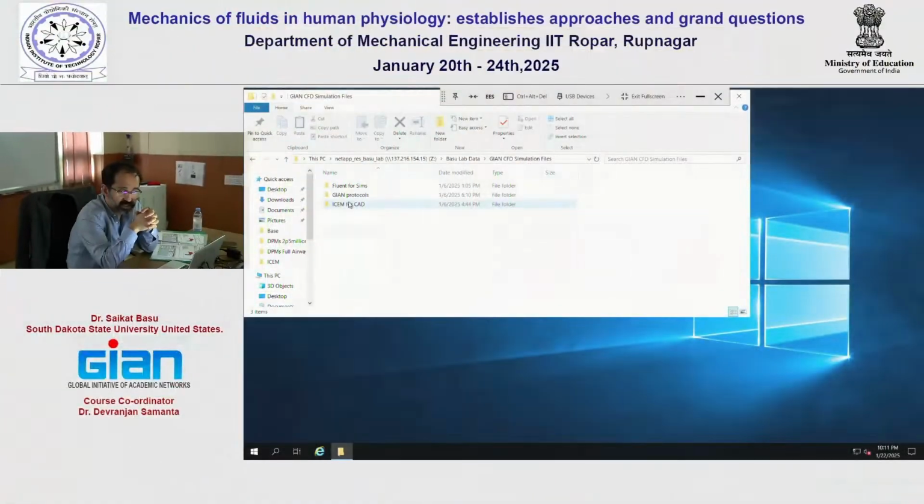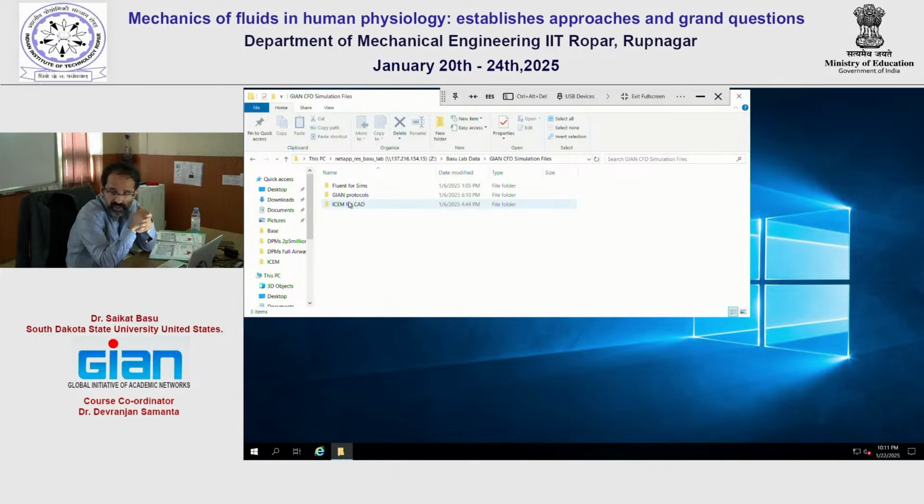But along with just meshing on the CAD software, we also do the region separation. So as you saw in the work that we have been doing, on the second day, I showed a geometry with all the sinus cavities marked out. You can do that on ICEM simply, or based on the question, you figure out what target sites you have to track in terms of particle deposition. So the geometry that I'm going to show today just has the nasopharynx marked out as a separate region, and the rest should be intact, the anterior airway. After the nasopharynx, there is a nasopharyngeal outlet as well.